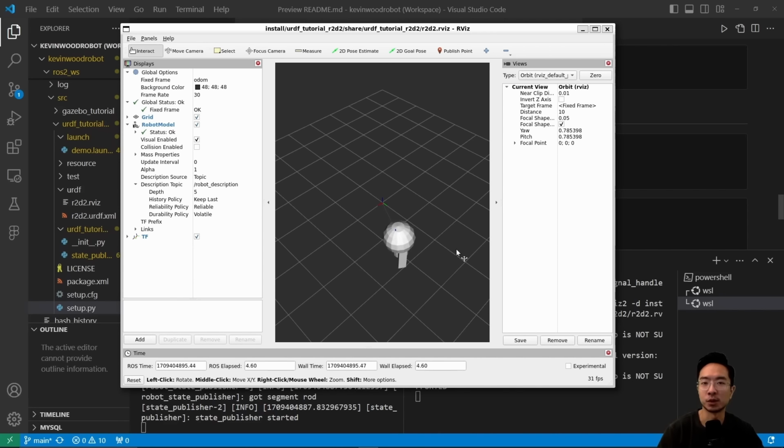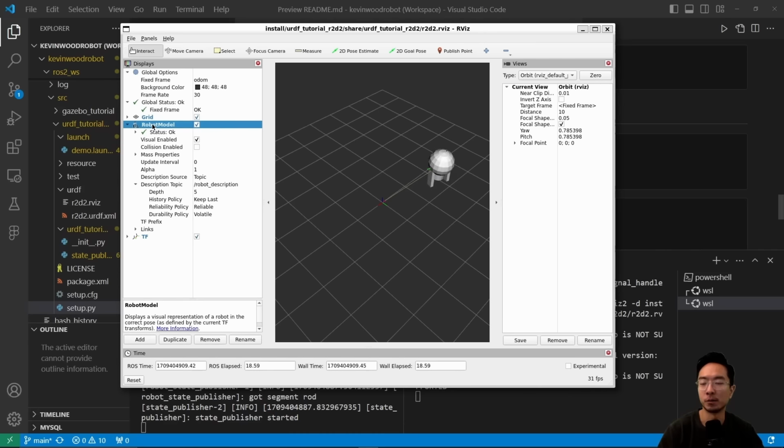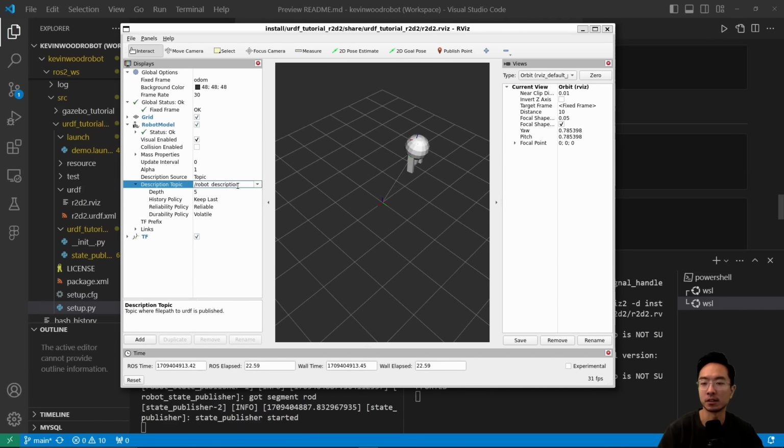So previously, we were talking about some of the settings you want to make sure your Rviz configuration has. So to actually see those things that we were talking about, you can see here is a fixed frame. So you want to make sure that's set correctly. And you have the robot model, which we've added in. And you see the robot description here is robot description for the description topic. And this TF transform is what allows us to see the transformation.